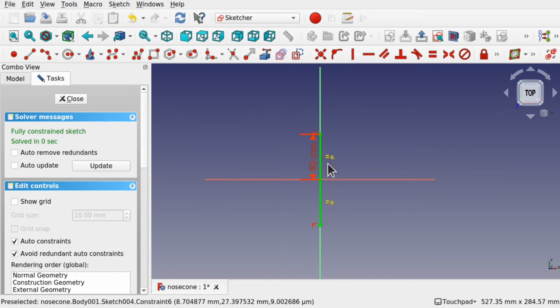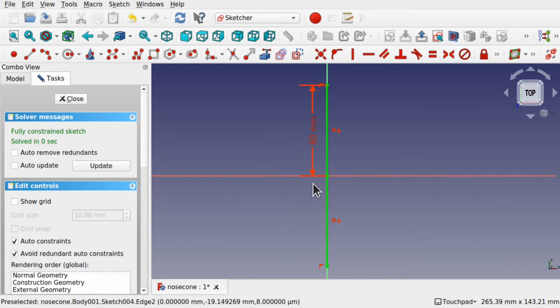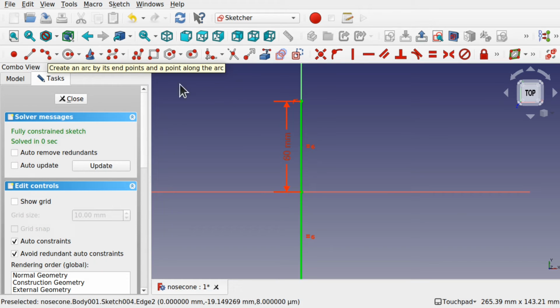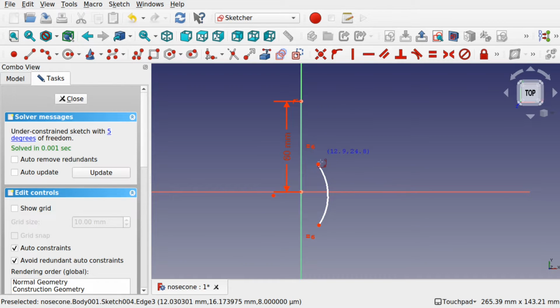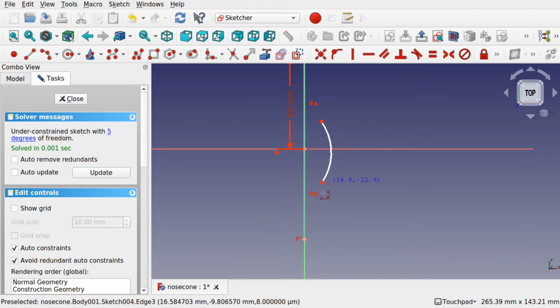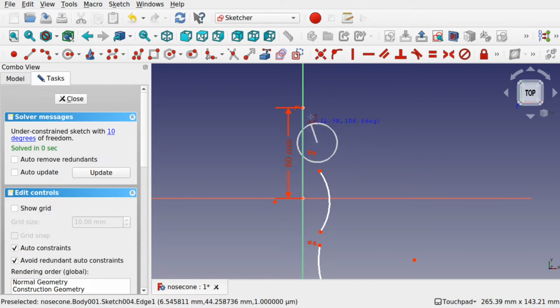Let's make the top profile. So this is what it's going to look like from the top. This is important to note how many arcs or lines we create in here. So I'm going to use this tool here, the arc, and I'm going to create 3 arcs. Again, remember, we're only going for a basic aerofoil. We'll get into more complex aerofoils later on, more complex wings. So the first one we're going to create is an arc, and then I'm going to decide how this is going to sit. So this is going to be like the nose part, and we're going to bring this around this way, like so, with a bit of curvature, and also bring this around this way.